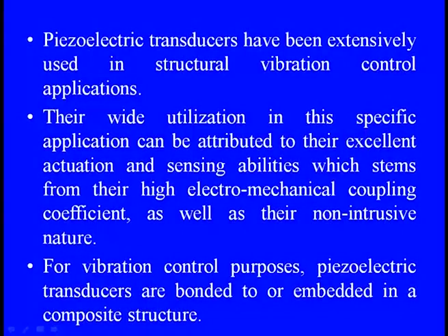So when we are talking about vibration control, we can use this material as a transducer. Piezoelectric transducers have wide utilization in their specific applications, attributed to their excellent actuation and sensing abilities, which stem from their high electromechanical coupling coefficient as well as their non-intrusive nature. Because of these two features, we can straightaway apply these piezoelectric transducers as sensors and actuators. From the vibration control point of view, these transducers can be bonded or even embedded in the composite structure, so that whatever is required, sensing or actuation, can act immediately.